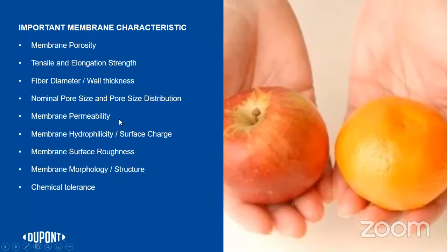I'll be spending more energy to get the filtrate out. Hydrophilicity of a membrane and the charge on the membrane actually govern permeability a little, because the more hydrophilic the membrane is, the more water loving it is, the impurities can be rejected by the membrane surface and the passage of water becomes easier. So the more hydrophilic it is, the better it is.